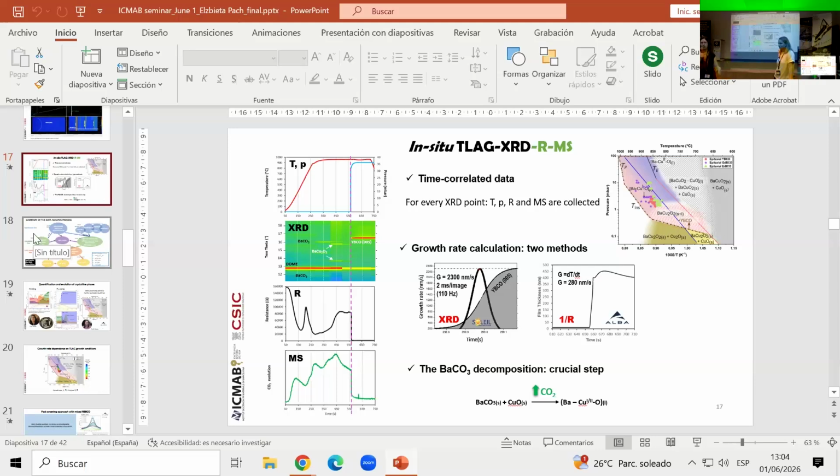Yeah, you don't see it. But also the point is that all the yttria that we put in the material is not dissolved in the liquid. Only a very small part is dissolved, and as we keep growing the YBCO, more yttria is dissolved in the liquid. So it's a semi-solid, if you like. It's a liquid with a lot of solids. And that probably also makes it still possible to measure this resistance.